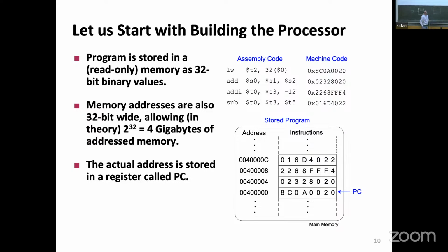And the register file, if you want to be efficient, I'll just try to be consistent with this. I have two read ports, and this is the first address. How many registers did I have in total? 32. How many address bits do I need to select one of the 32? 5, so 2 to the 5 makes 32. So with a 5-bit address, I can pick one of those registers. And the register output, just making sure that is the read one, will be a 32-bit value. This is the content of the register that corresponds to this first address.